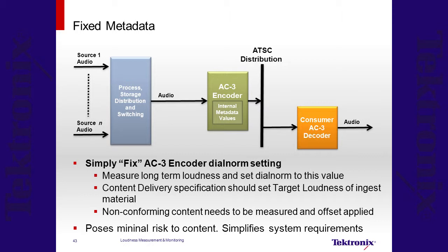The content delivery specification should set the target loudness of the ingest of the material, and any non-conforming audio needs to be measured and an appropriate offset applied in order to conform to the transmission requirements. This approach poses minimal risk to content and simplifies system requirements.